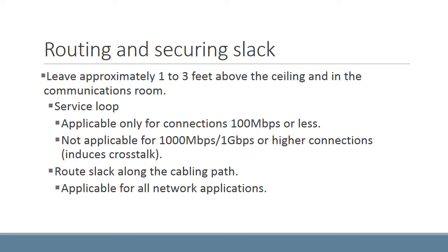When routing and securing slack, leave approximately 1 to 3 feet above the ceiling and 1 to 3 feet in the communications room.